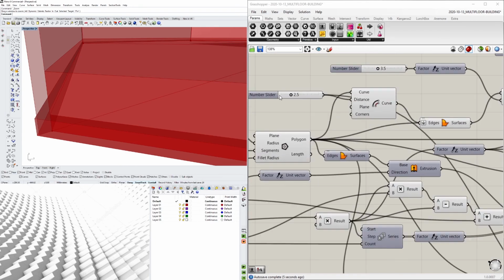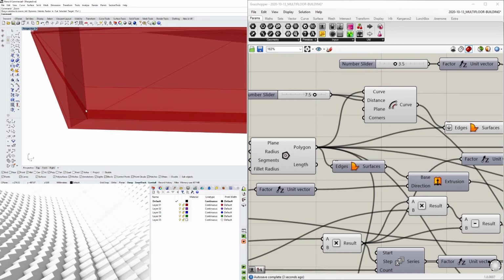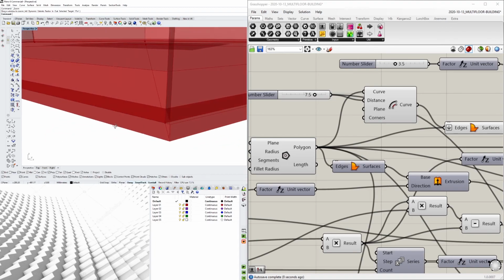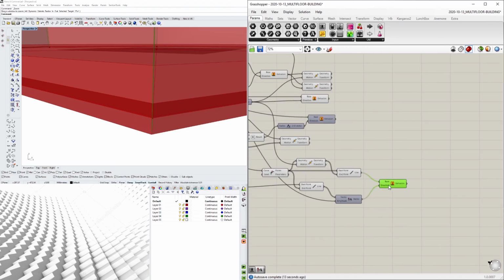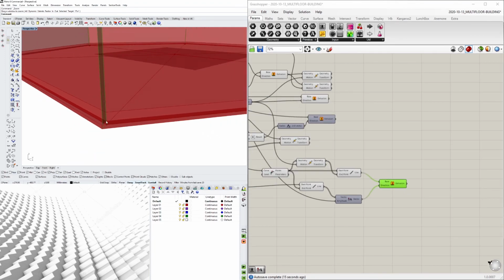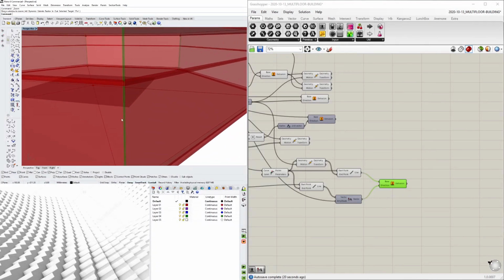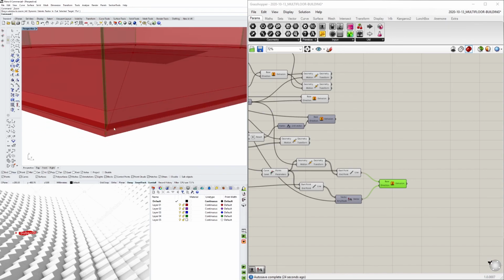So no matter how big our offset is for our bottom base, this will always come a little bit less than that. Why? Because we're also going to extrude this in both directions. So here's the thing. Once we have these, which is good, we want to extrude them in both directions. Now, what I don't like to do is extrude in the positive and negative and then put it together. I like to actually move it in one direction and extrude it twice as much.